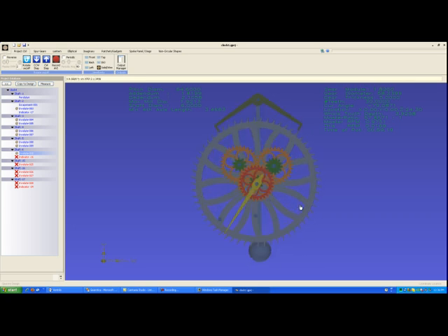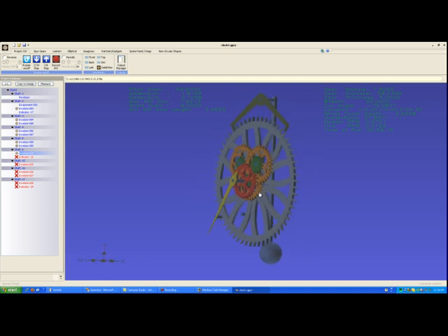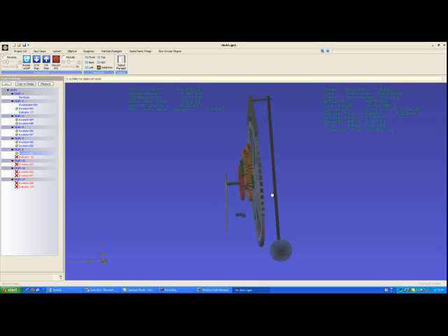The reason that you want a separate shaft for a gear, even though they're really sharing a shaft, is that you can only place indicators on shafts, not on gears. And you can't place an indicator on a shaft which is sharing 2 gears. The indicator wouldn't know which gear to use. So in this case, I've created its own shaft, shaft 6 here on the side, as you'll see when you load the project. The project is included with Gearotic Motion at this point, so you can build as many of these clocks as you want, or use it as a basis for building your own clock.